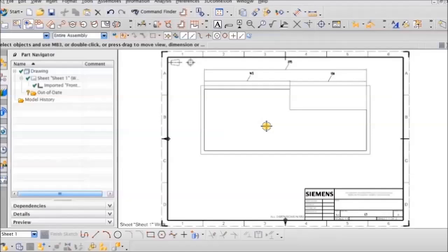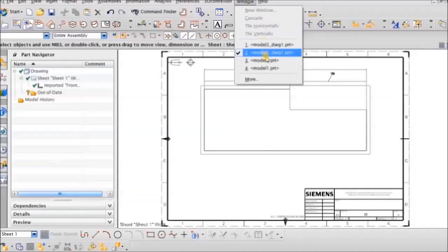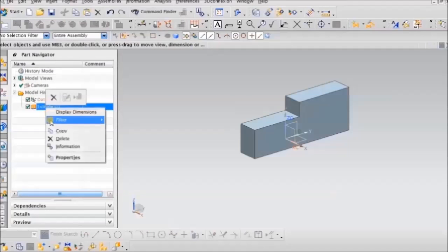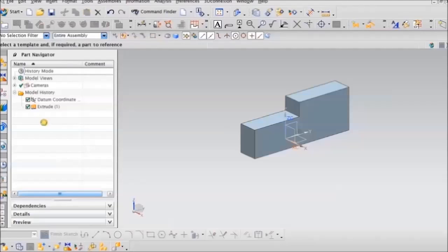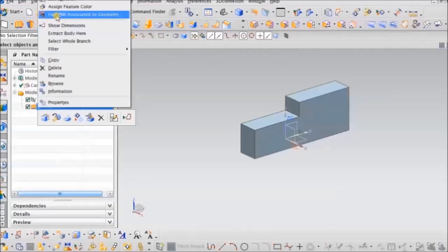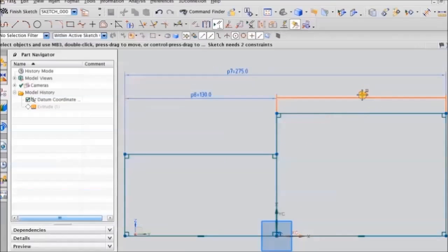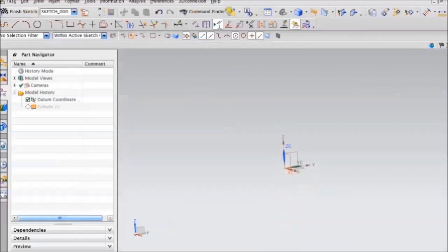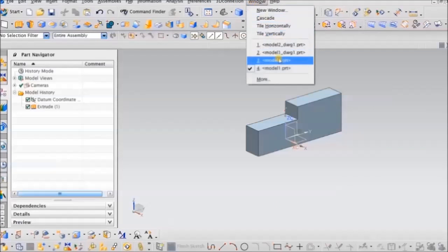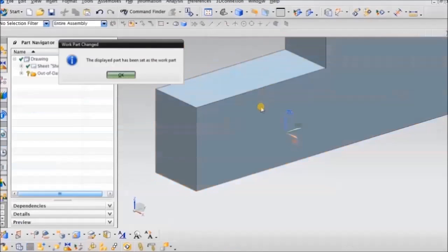And in case you don't have one parameter on the sketch, you can actually define it as a reference dimension inside the sketch. As I can see here, one of the dimensions is a reference, but despite that, it is shown on the drawing.